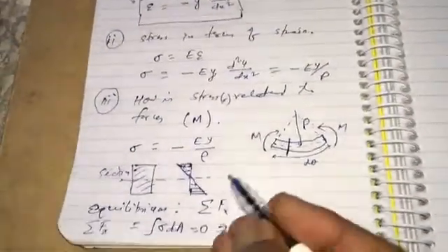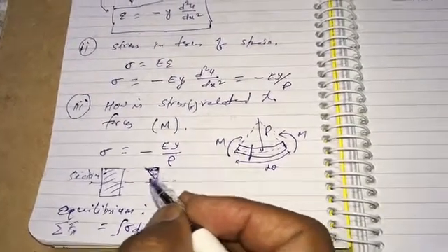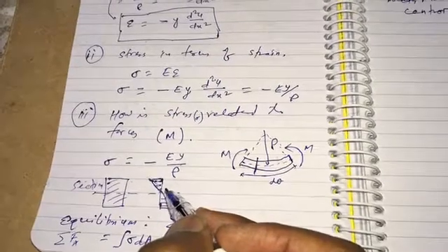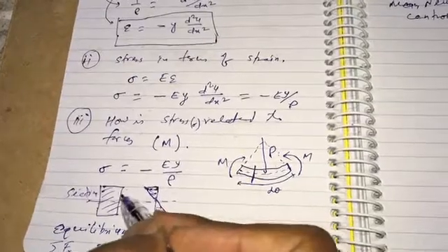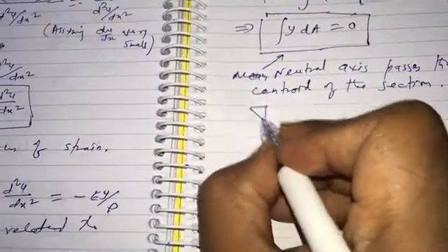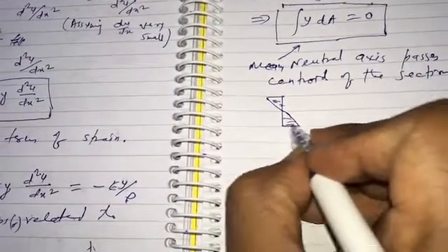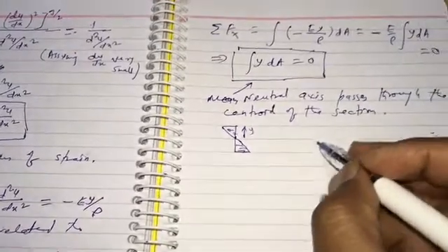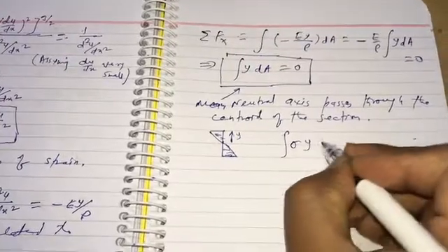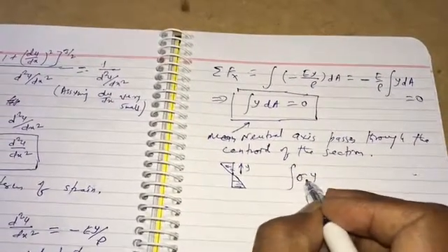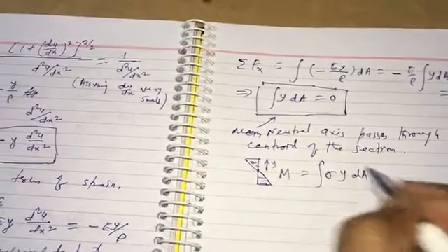The second piece of information, the second equation of equilibrium, we can get if we apply the bending. So we want to find out that the total bending moment is equal to M. At this section the bending moment is M, hence we have to integrate sigma over the whole section, and that should give the result equal to M. So if the profile of the bending is like this, and y goes from here like this, then sigma times y is the lever actually. Sigma times y times dA, this is the bending moment M it should give.